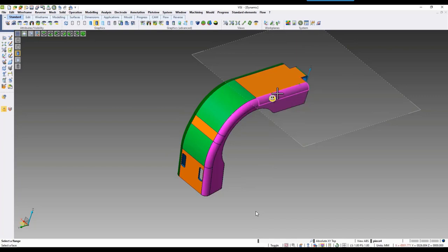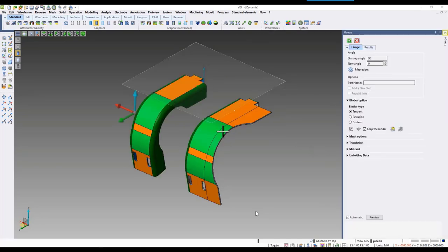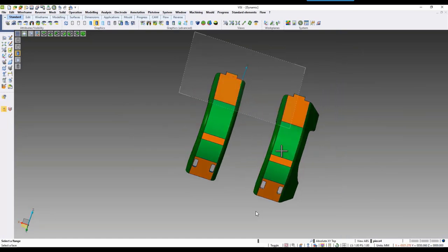So we do the part unfolding on a flange, and we select it, let it process. It's going to basically build the information off of that. We can then see that it's automatically updating the colors after we've unfolded it. If you go into the 45-degree angle and map the edges, you can see how we still have our mapped edges and relevance to it as well. So it'll automatically update it, and then we could do a two-step flange on these specific areas.